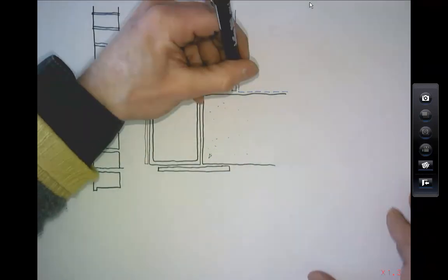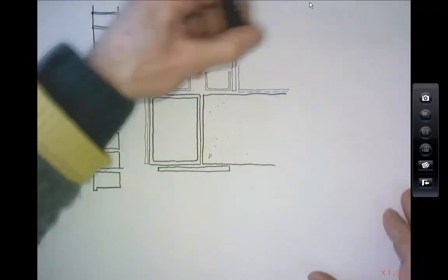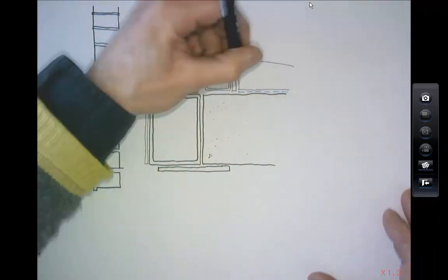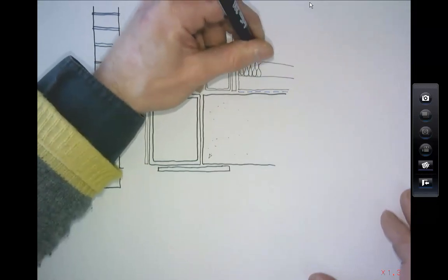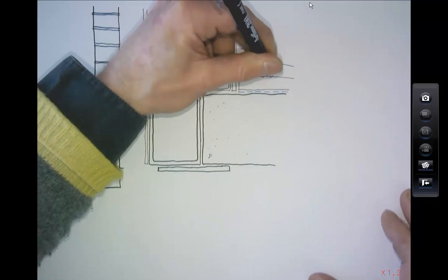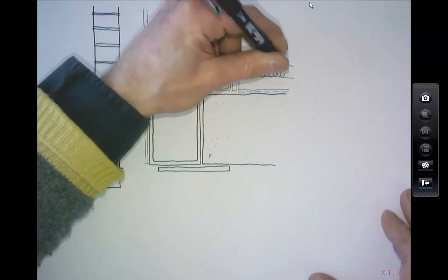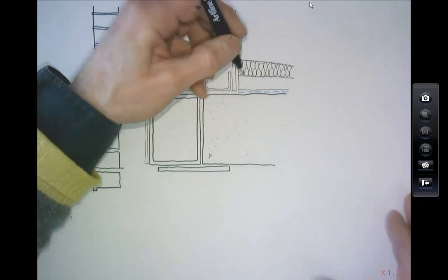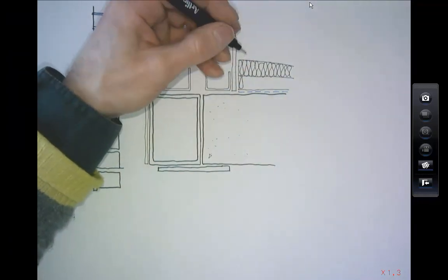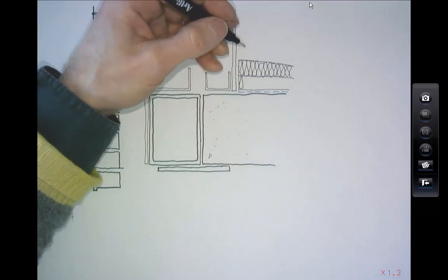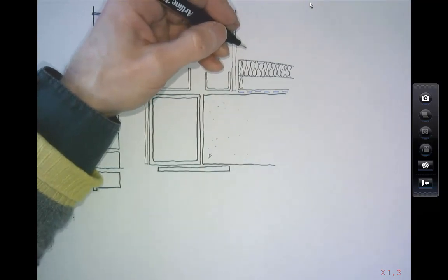Then, in this case we used tapered insulation, and when you get out into practice, tapered insulation is great because it means all of your structure, all of your concrete can be flat. And that's much easier to draw. Everyone will thank you for that. All your engineers, everything's flat. People hate it when everything's at a different level.